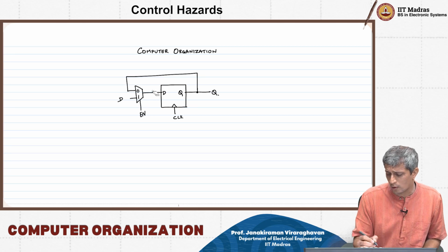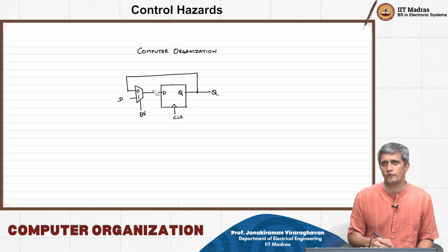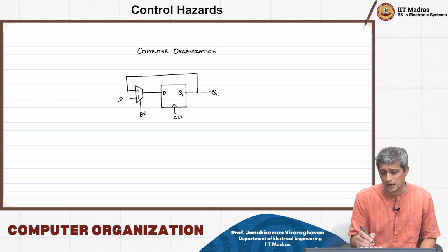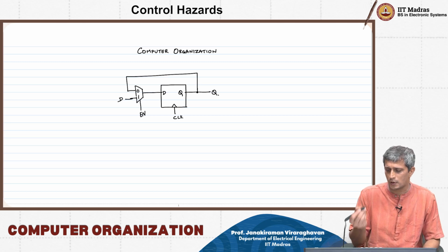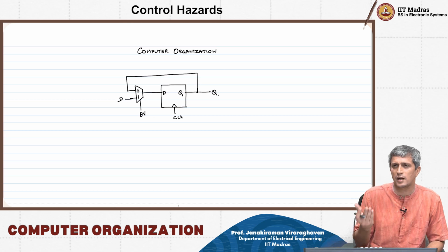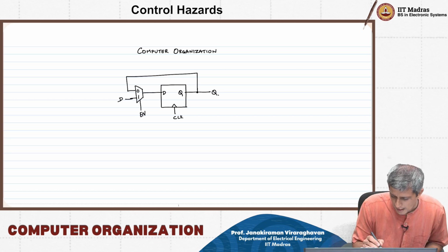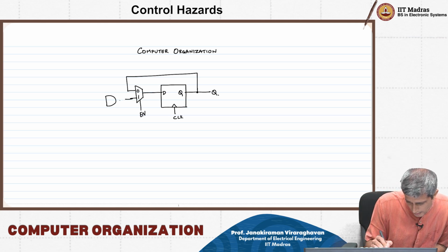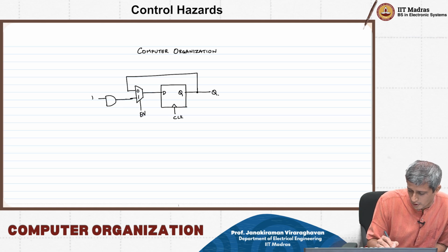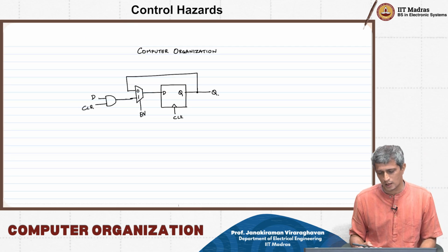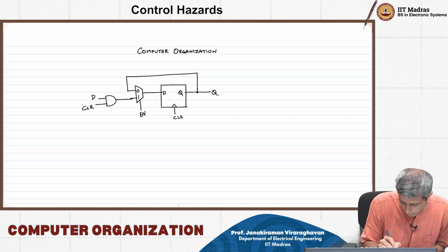On the other hand, now I also want to implement a flip-flop with a clear. So what is the clear signal? The clear signal can be implemented again as a synchronous clear or an asynchronous clear. Synchronous is usually better, and you could do this in multiple ways. You could just put an AND gate here, you give a D and then you do a clear. So you want a clear here, which means I will say clear bar.